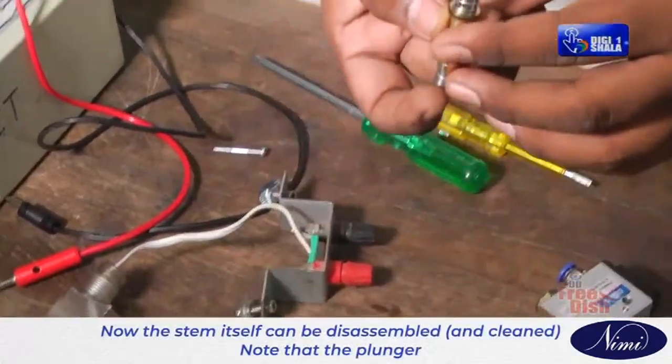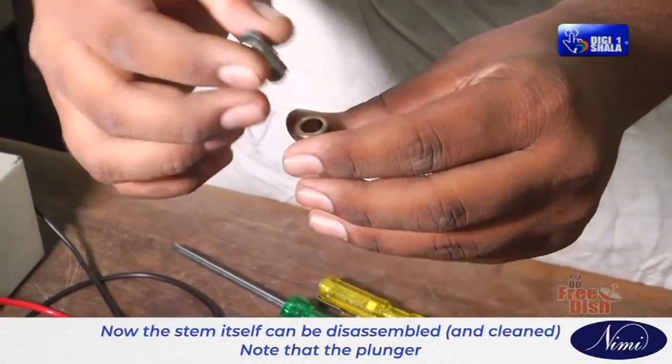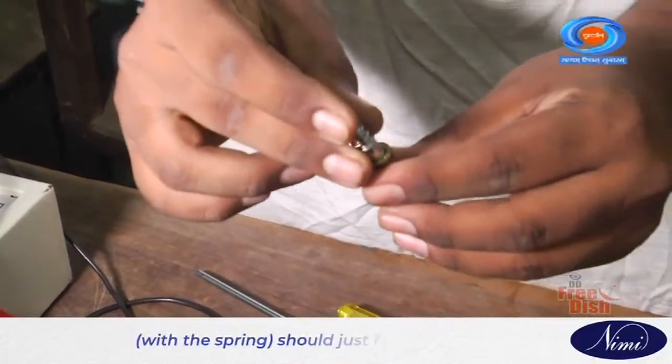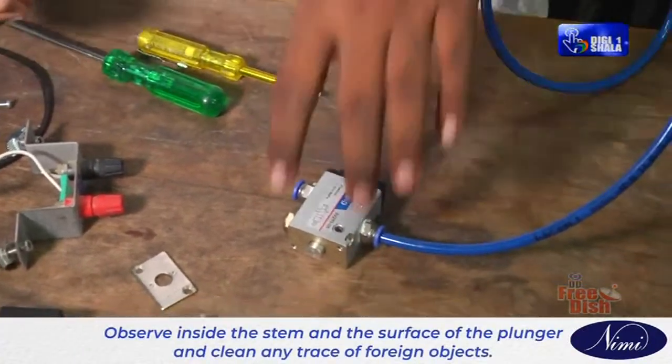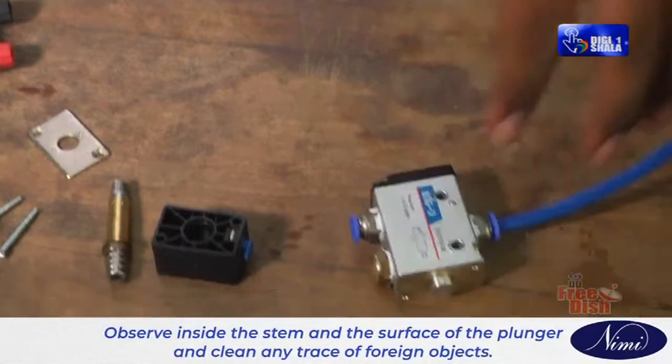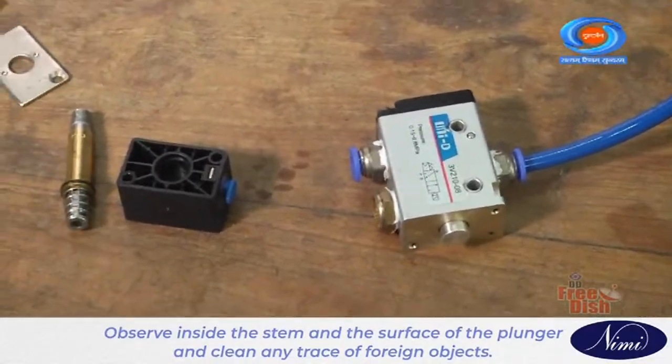Step 7. Now the stem itself can be disassembled and cleaned. Note that the plunger with the spring should just fall out of the stem. Step 8. Observe inside the stem and the surface of the plunger and clean any trace of foreign objects.